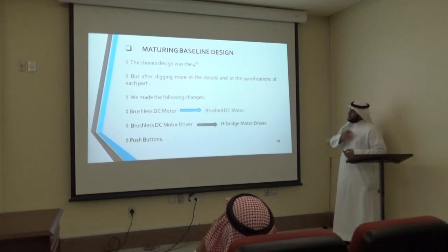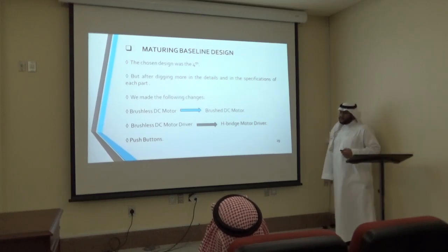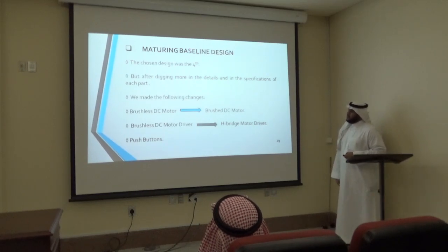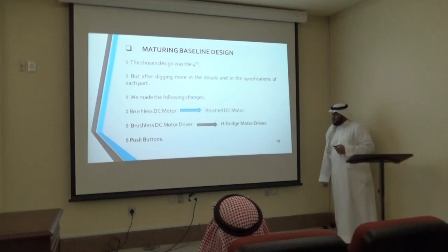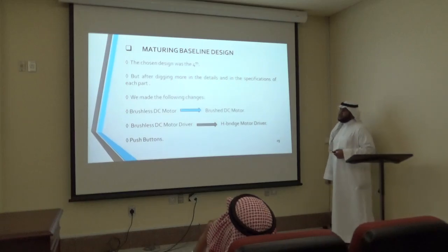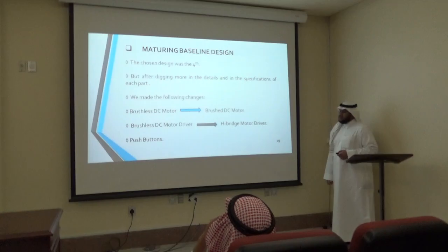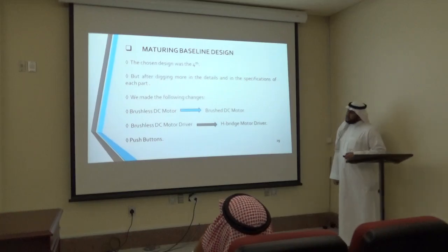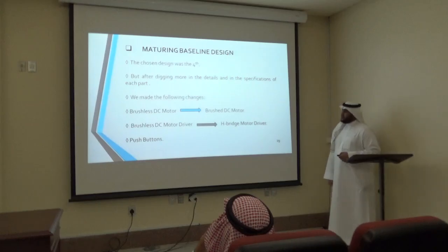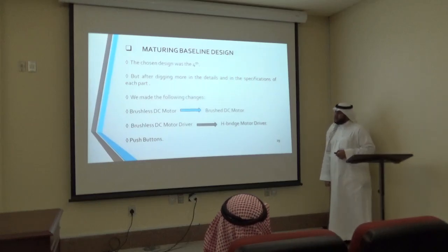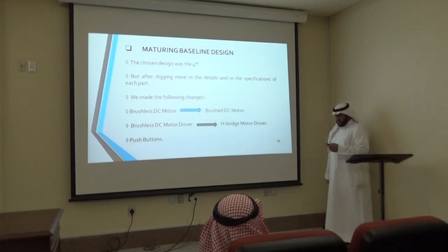After digging more into the details, we have made some changes to the design. The first one is that we have replaced the brushless DC motor with a brushed DC motor, because the brushless DC motor has more complexity to implement than the brushed DC motor. Also, the brushless requires a higher cost, and the efficiency between them is about the same. The brushless is better, but not by as much as we need for our project.